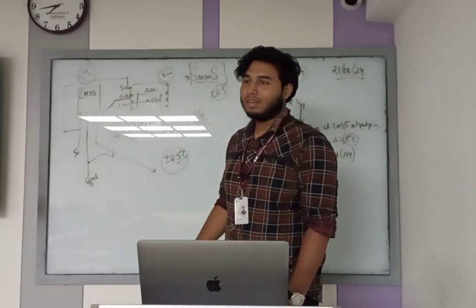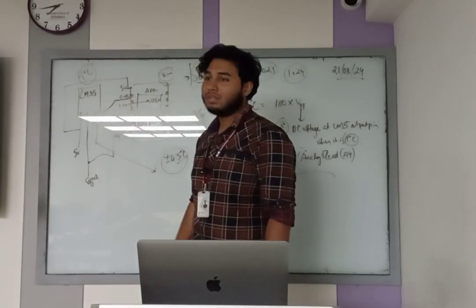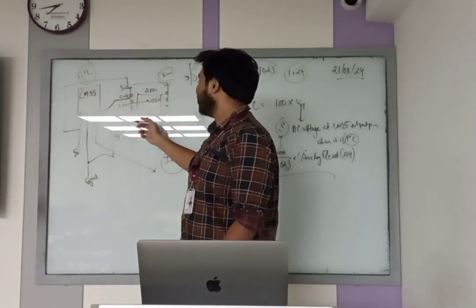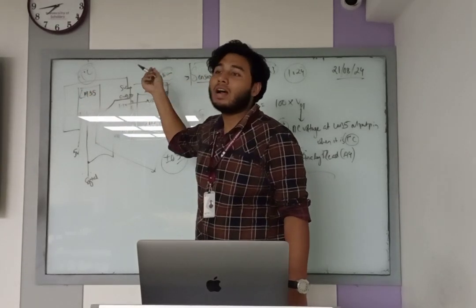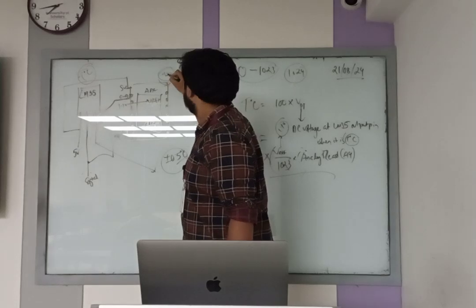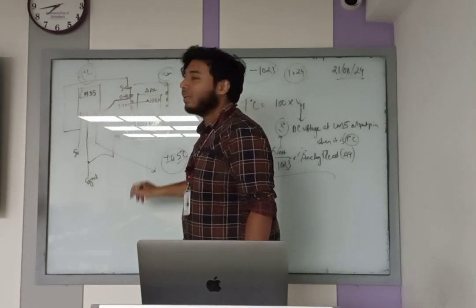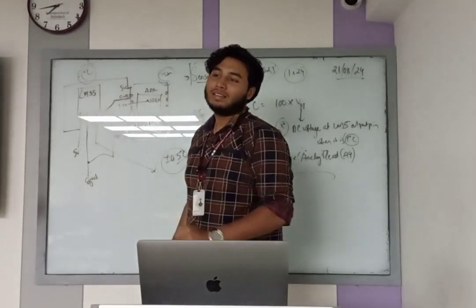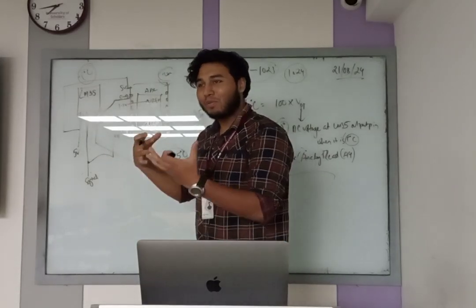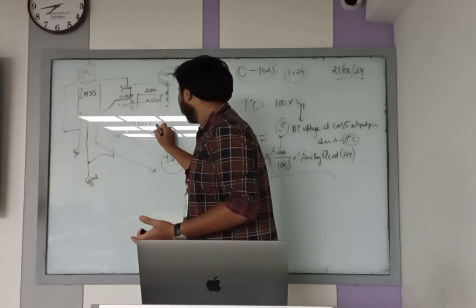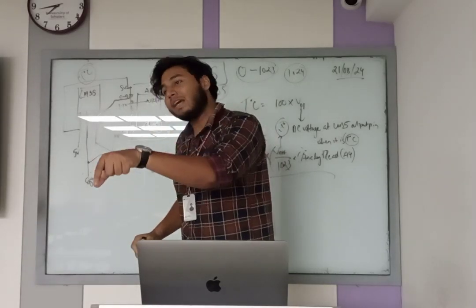Simple. Arduino Nano, channel 5, A5, and all the rest should be the same because you are not going to change the LM35. So you have just changed the Arduino. If you write the Uno, if you write 4, then I will understand you have memorized this. But that's not the memorizing thing. That's the important thing you have to learn: I am talking about channel 5, and I am specific about channel 5.